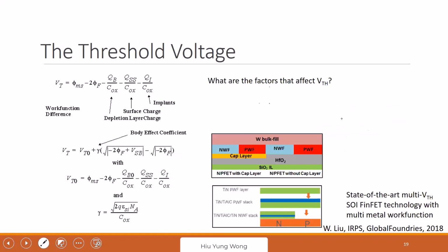Then we discuss so many concepts. Again, that is how I teach this class, right? Well, it's not device physics. Then we jump to the final equation. There's no need to derive this equation. What we want to know is what are the factors affecting the threshold voltage? That is, again, what is the threshold voltage? It is the VG after which you only form the inversion layer. You no longer deplete. You're doing something useful for the current conduction. Okay, so what are the factors that affect the VTH?